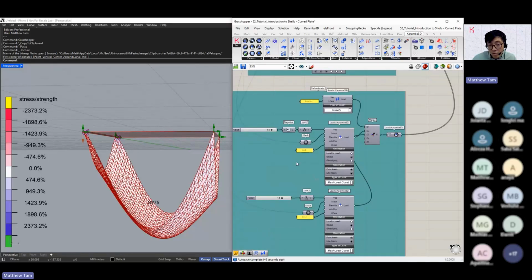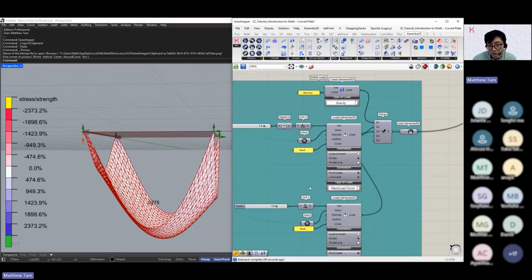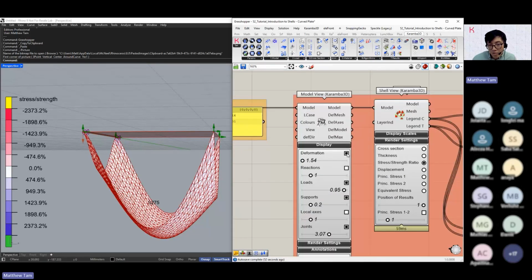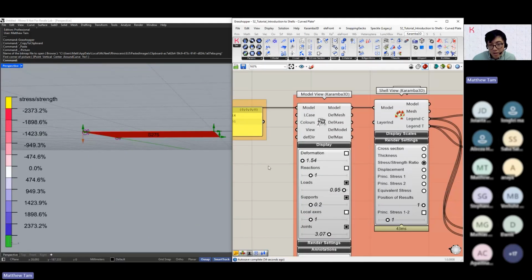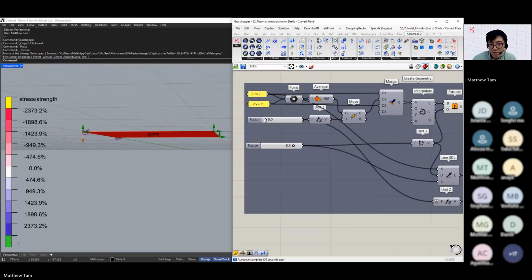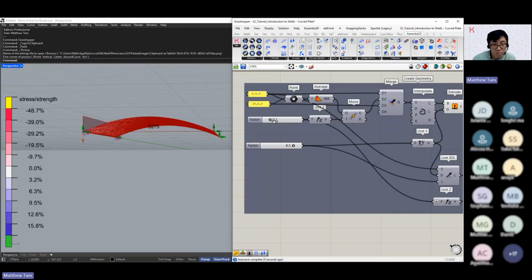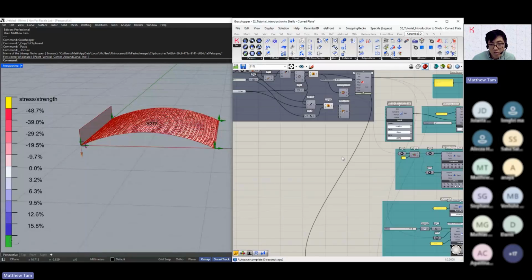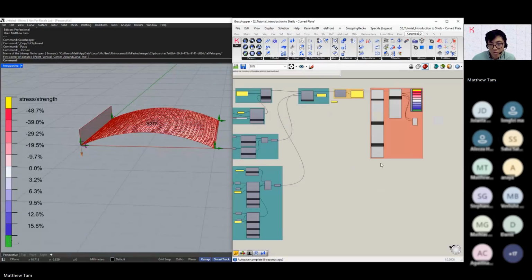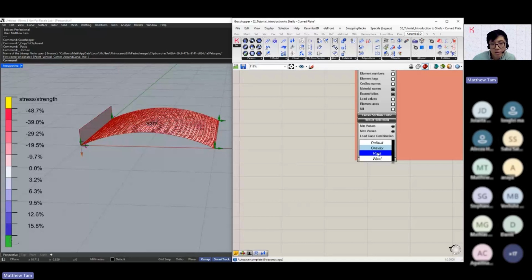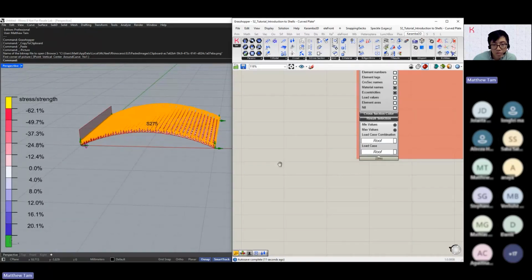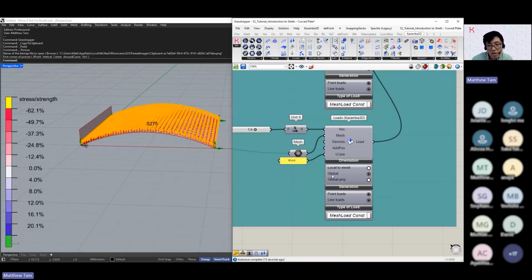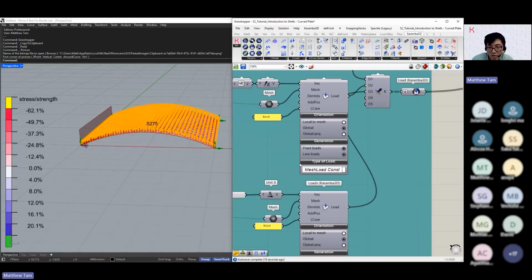Lastly, I wanted to just go over the loads. So let's turn off the deformation, and let's set our height to, for example, 1.2. And let's have a look at the roof load case. Let's see what happens when we change the orientation of our roof load case.